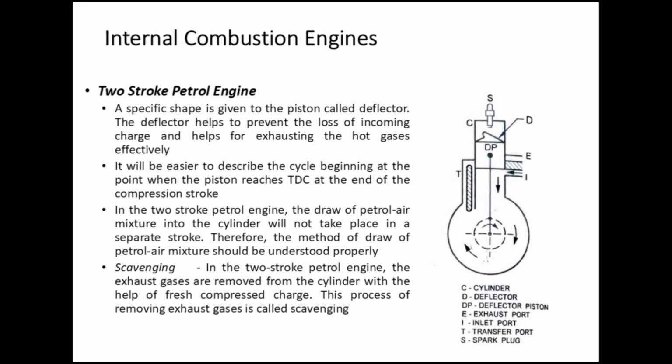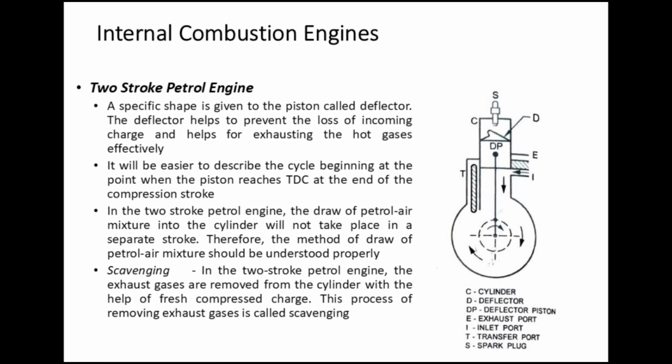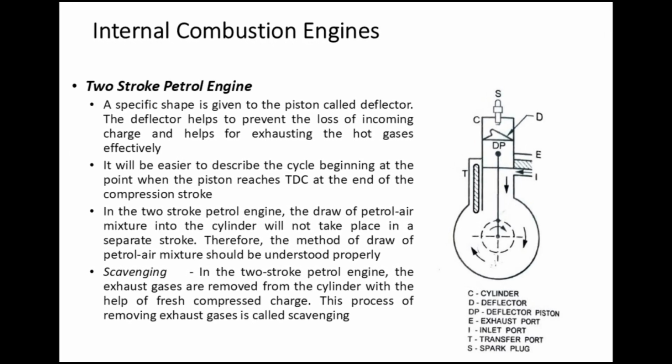Internal combustion engines. Two-stroke petrol engine. A specific shape is given to the piston called deflector. The deflector helps to prevent the loss of incoming charge and helps for exhausting the hot gases effectively. It will be easier to describe the cycle beginning at the point when the piston reaches TDC at the end